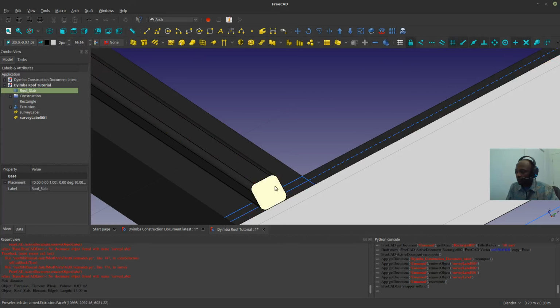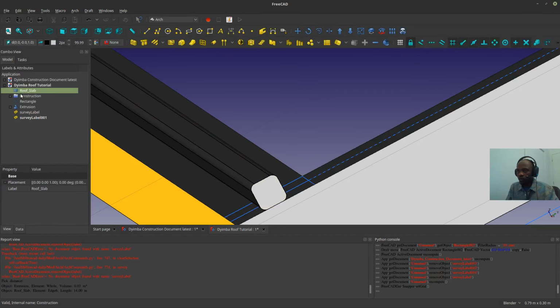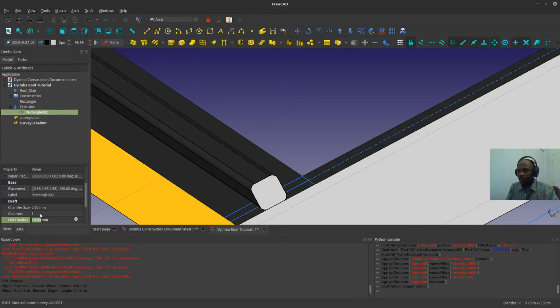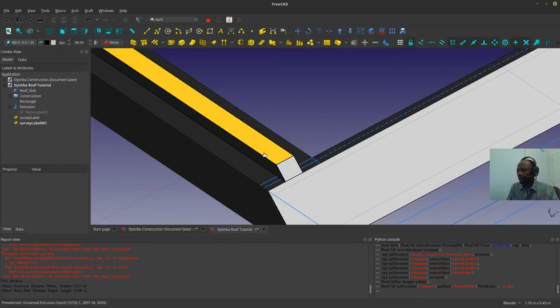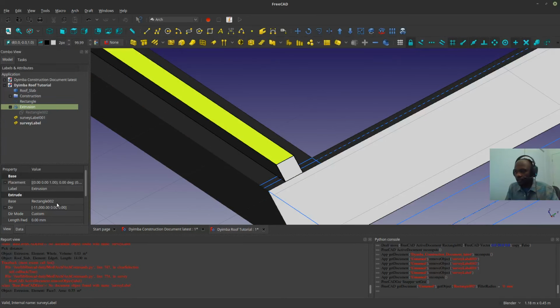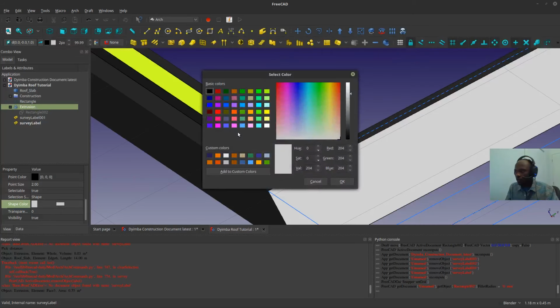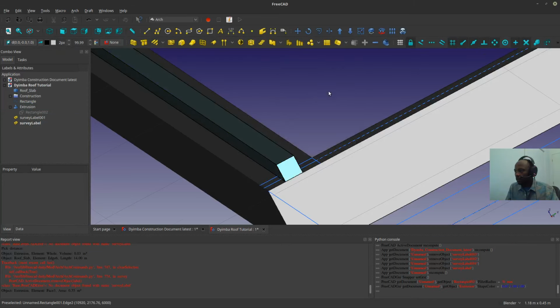It's probably confusing to the eye, so I'm going to remove that radius, go to 0. Okay, and I'm going to color this so that it's easy to distinguish while we're working. Some kind of blue like that.